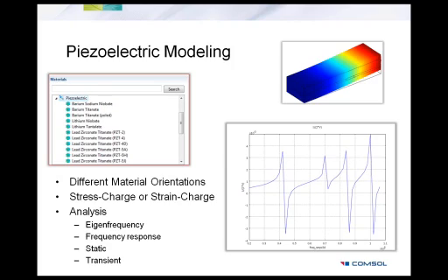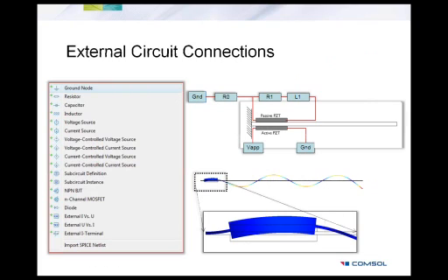Okay. That being said, COMSOL's MEMS module also gives you an external circuit link. This is basically for including circuit elements in your model. Let's say you are interested in modeling a resonator's physical characteristics. If you want to build an oscillator around it, this can actually be done very, very easily. You model the resonator using this module, then you connect this model to an external circuit to simulate the complete oscillator with a feedback loop.